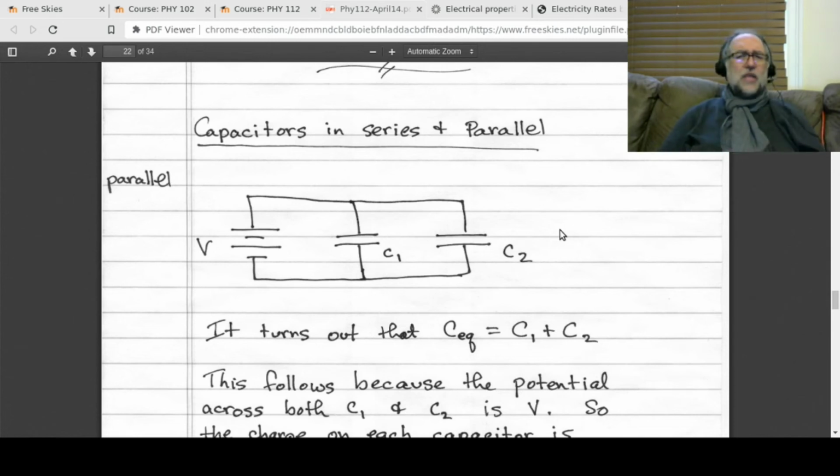But currents are not that interesting with raw capacitors. There are going to be currents as they charge up, but they're going to be very short-lived, transient currents. So this isn't going to be something like Ohm's law where we're talking about currents. Here, the three things that are really of interest are voltage, capacitance, and the accumulated charge. You could think of that as the equivalent of Ohm's law, but for capacitors. So V is the same across C1 and it's the same across C2.